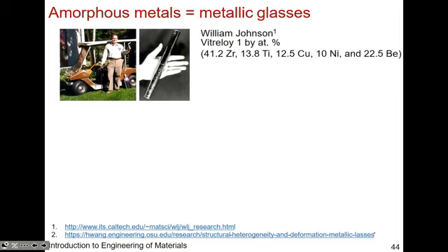So metallic glasses, as I've said, glasses can be made of metal. So what happens when you combine a whole bunch of metals together? We've talked about the Hume-Rothery rules, where if you have similar atomic radii, similar electronegativity, the same valence, you can form these solid solutions and they mix well and they crystallize well. Well, the alternative is you have a bunch of elements that don't satisfy any of those rules. They don't mix well, they don't crystallize, and you actually get increased stability.